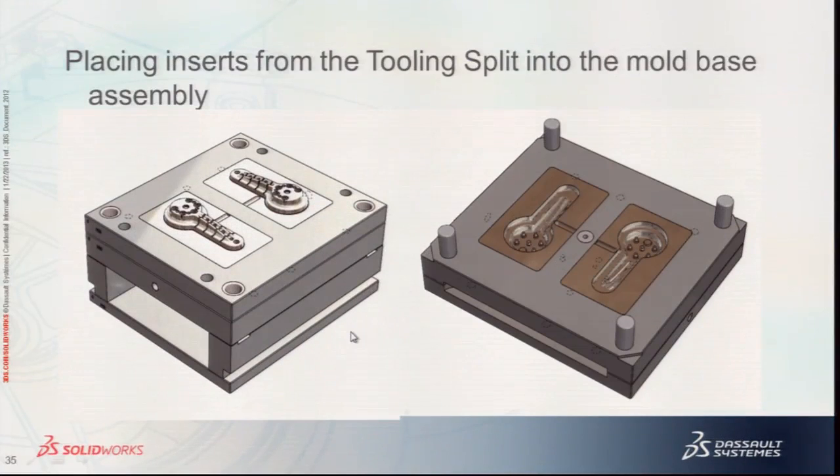And what I'll do is I copy that around to the other side using a pattern, a circular pattern based off the center axis, and then I cut away in that B plate, just in context, cut in the B plate down to whatever thickness my insert is, and you fine tune the geometry based on whatever tolerances you're using and clearance and whatnot. And that's how you basically place it in there.